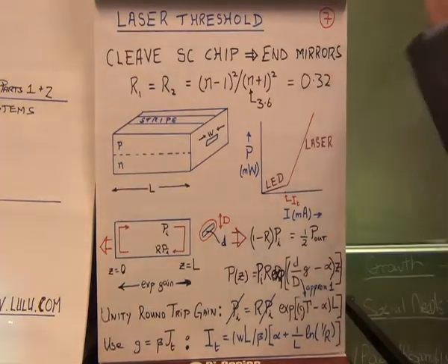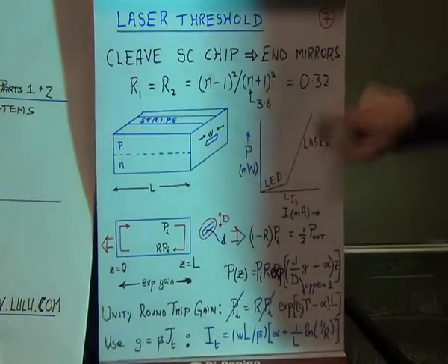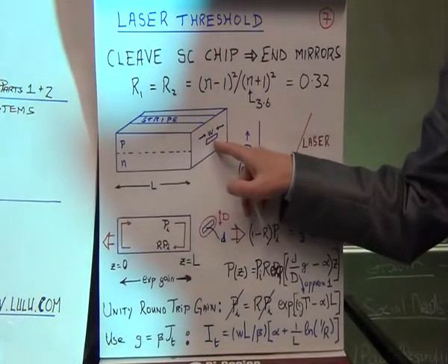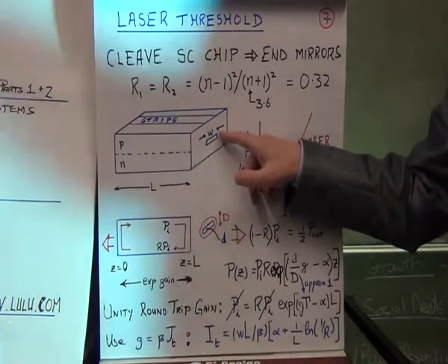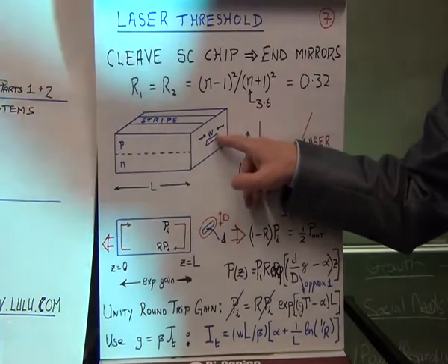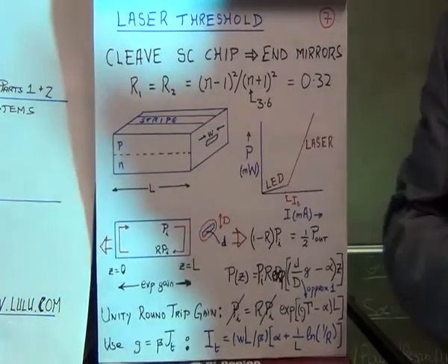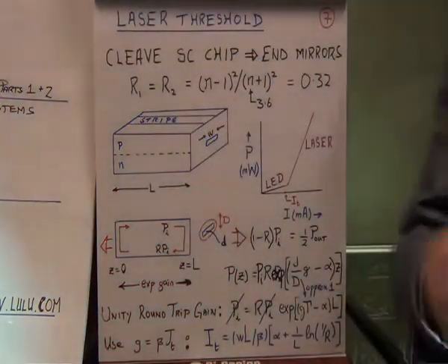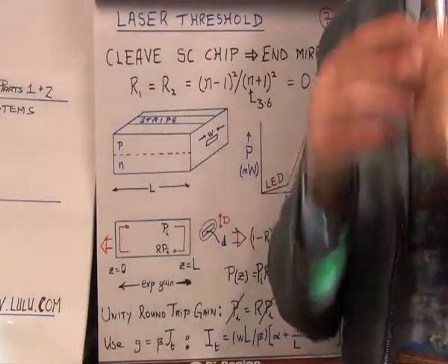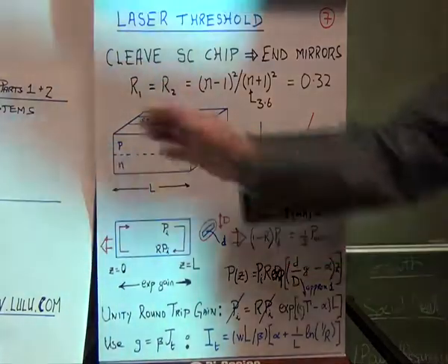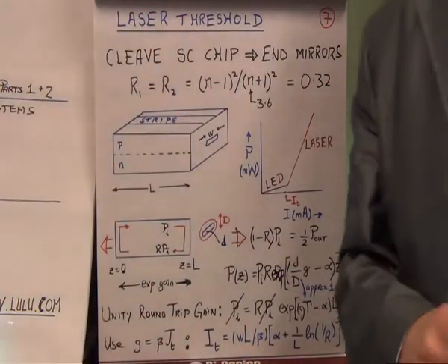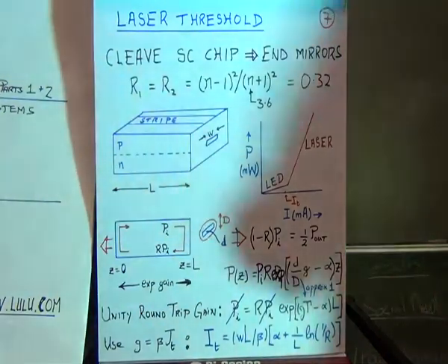That surge is enough to give a surge of drive current such that the intensity of light at the facet is higher than that on the surface of the sun. That can easily happen, and you just burn a hole in the laser chip, it's dead. So you must always have very carefully controlled current drivers driving these lasers. You must be monitoring them all the time. You must make sure there's never any surges of any kind, or they're all dead.